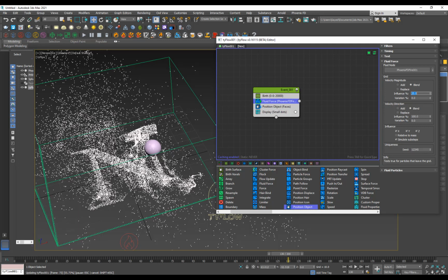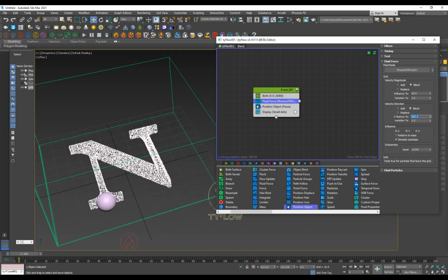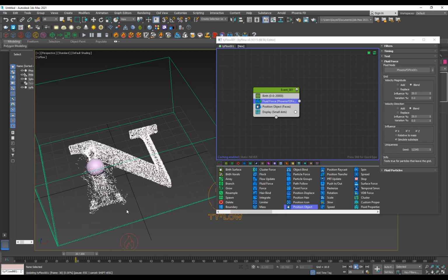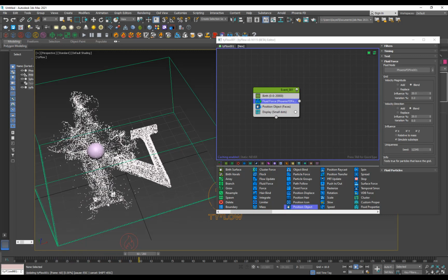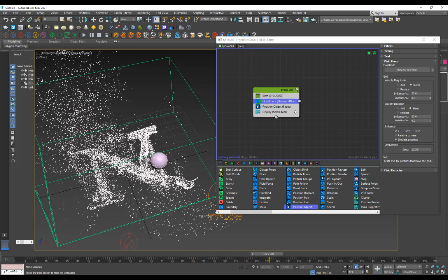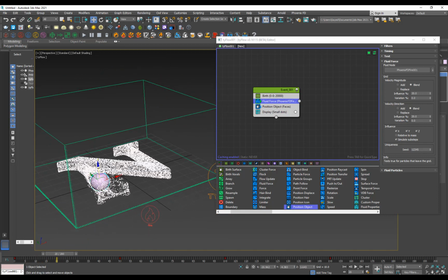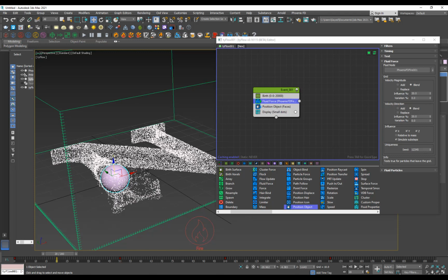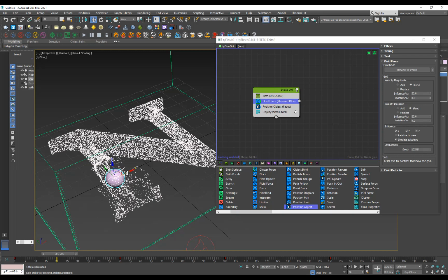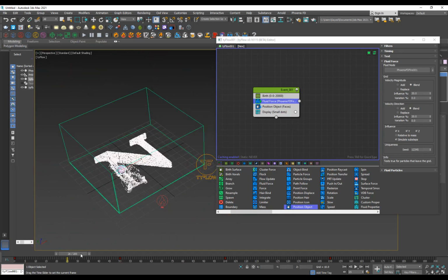and the direction 2. So just make sure when you update the parameters, go to the first frame, and make the parameter 20. And then let's see here. Now it's not going that wild, hopefully. But if it is going very wild, what you can do is make your emitter object, the object that is used as an emitter for the Phoenix FD, smaller and re-simulate it, and hopefully that'll be a little bit less intense.